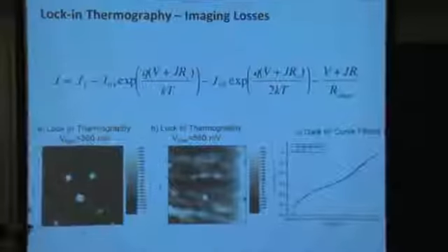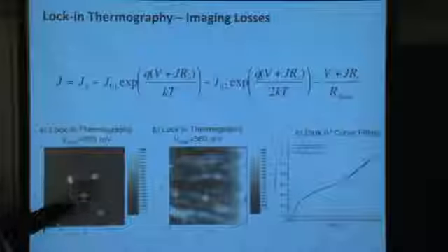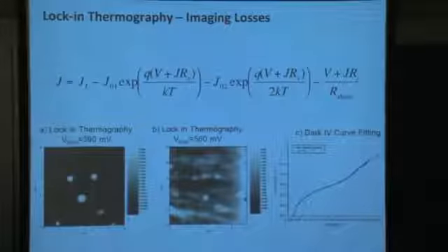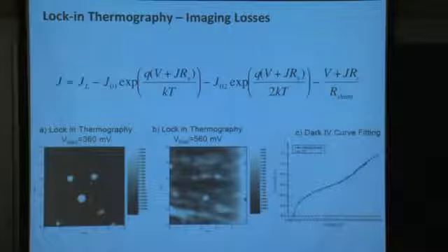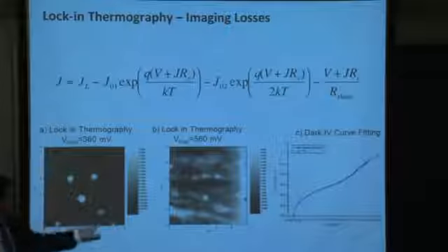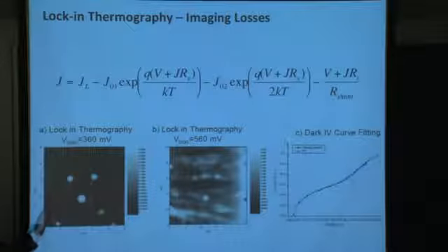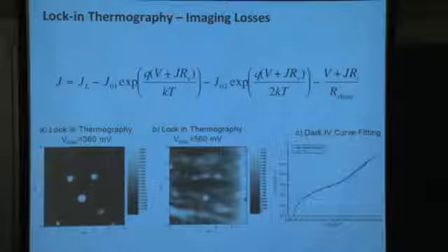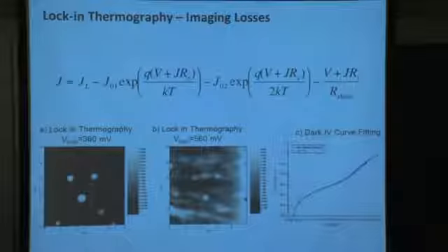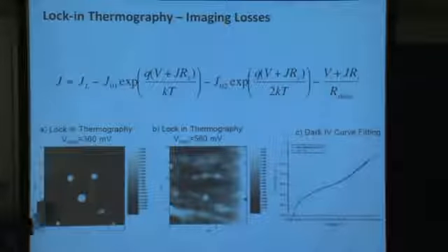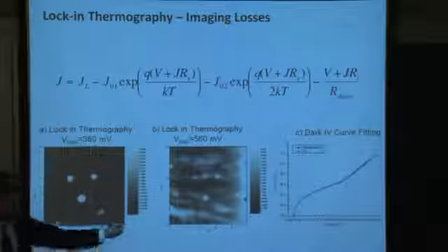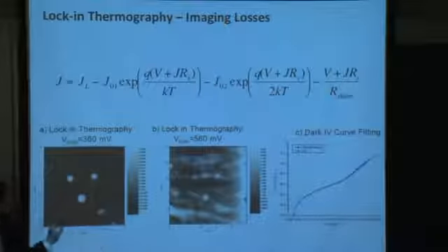So under low bias conditions, I still have a very large barrier there in the p-n junction region. I'm typically going to see isolated hotspots, not always, but typically isolated hotspots. And these, most often, are defects within the p-n junction. Somebody must have scratched the junction or maybe dropped their tweezer on it, or maybe a piece of metal during the contact metallization fired through at that particular region. And so we have what are typically these point shunts. Sometimes you see shunts around the edge as well, if you didn't isolate the edge well.